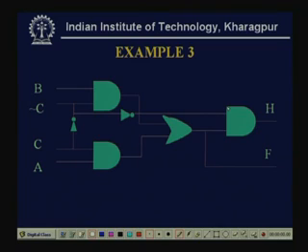So, this OR gate is nothing but our previous example, it is giving the F. Now, I have included another inverter whose input is C bar, so this input is actually C, and another AND gate is included. So, this is FC.